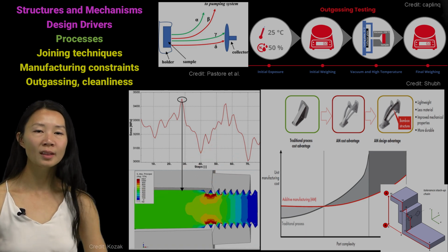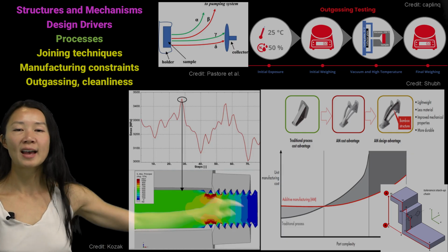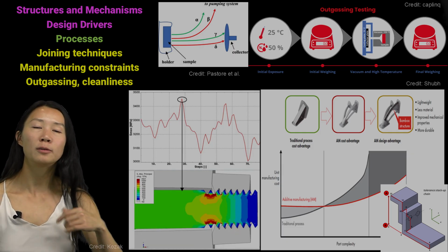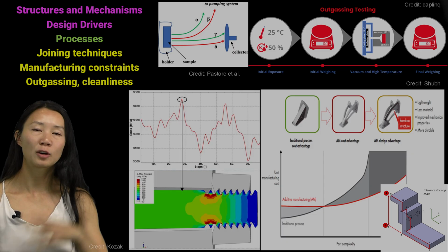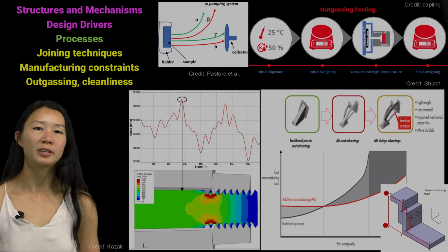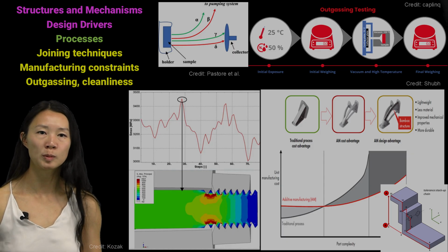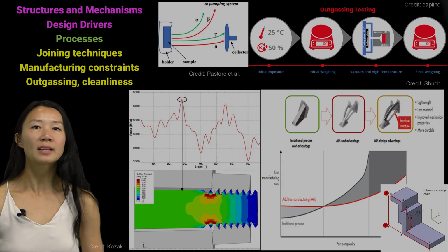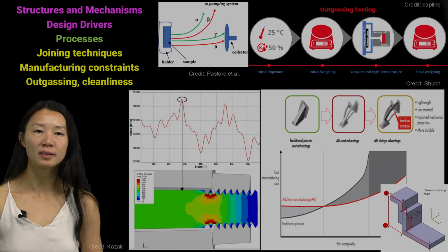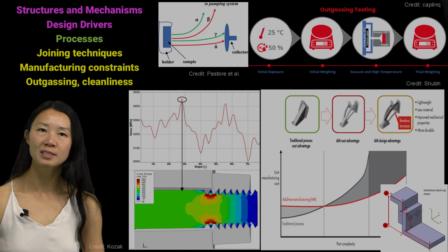Also note in that figure on the bottom right how tolerances stack up across parts. Even small machining errors can add up when assembling multiple parts in sequence. That's another reason why additive methods, which can print integrated geometries, are gaining popularity in spacecraft design.